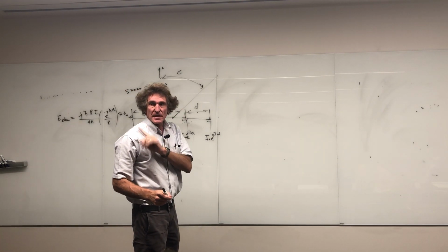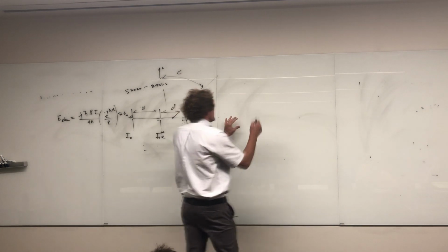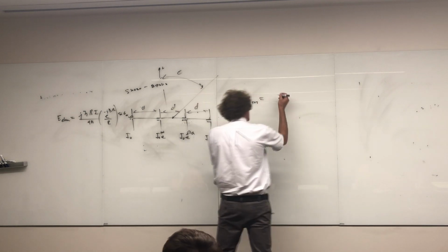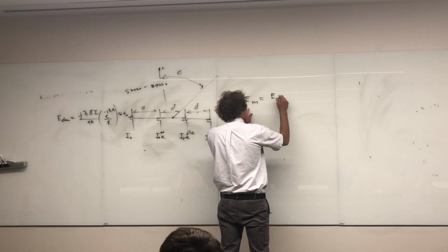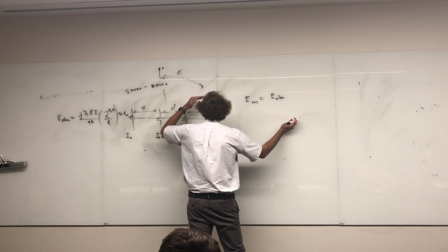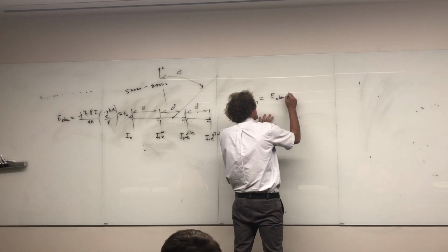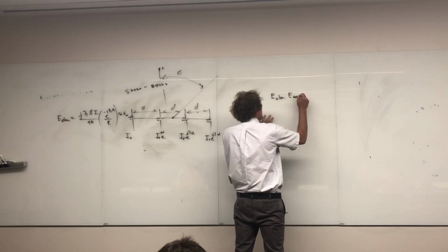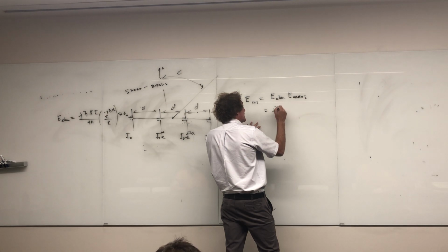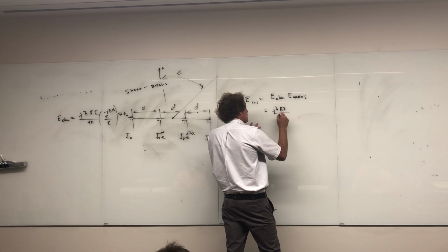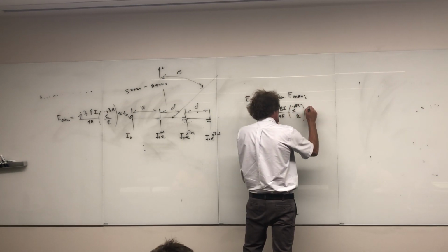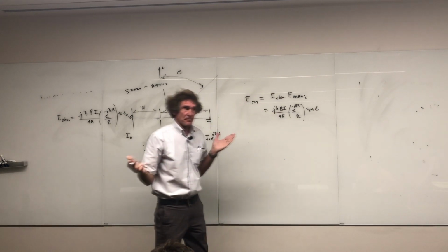Now to get the antenna pattern caused by this, the total E field for the array would be equal to the E field of the element that I just put up there. And remember, this angle becomes critical. Theta is measured from the z-axis over here, times the actual E field of the array. You could say it's the array effects. It's these two. This is the way it appears in a lot of books. Well, the element we got, it's j eta beta I over 4 pi e to the minus j beta r over r, then times sine of theta. Follow me? That's just the element.